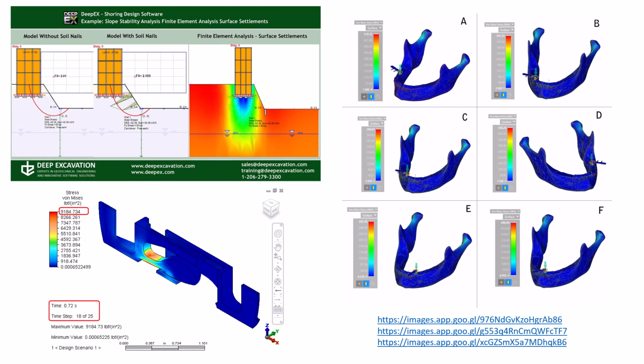So, finite element analysis 101. The way that finite element analysis works is it's a technique that's utilized to perform, among many other things, but first and foremost, it is used to perform stress analysis of odd and unique situations. Basically, we take a given component or a given system and we discretize it into a series of discrete regions that we call elements. And we assume what the solution looks like across those elements. And so the more elements we use, the better the answer we get. So there's a whole body of research focused on taking complex scenarios and applying finite element analysis techniques to determine worst case stresses and worst case scenarios.